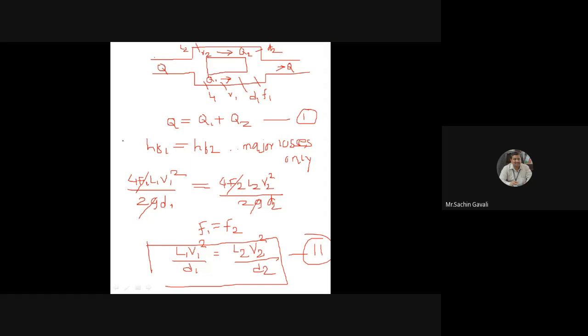The total head loss is equal to the sum of the head losses occurring in each pipe, and the discharge is the same. In parallel pipes, the discharge is different, and the main discharge is equal to the sum of the discharges flowing in each parallel pipe, and the head loss for each parallel pipe is the same. For series pipeline connection, the head loss is the addition of all the head losses, and the discharge is same. Write down. If it is over, please tell me over.